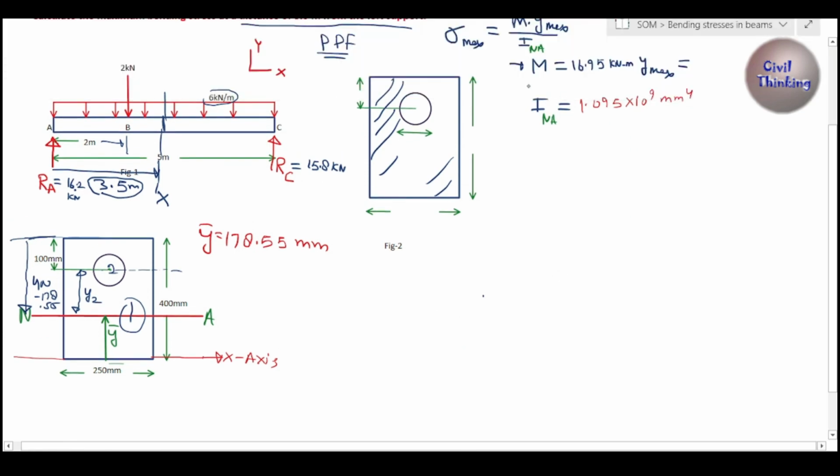Okay, now we know the moment. We know the moment of inertia about the neutral axis. We know this M. We know INA. Now we just need y max. Okay, the moment we get y max, we can find the bending stress. Now, how to find the y max?